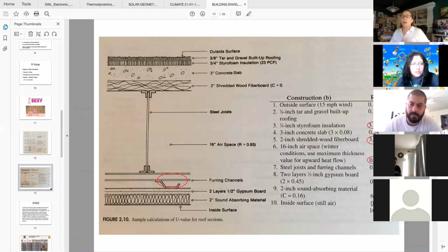Another example. I actually worked on a house on Bankers Hill here in San Diego that was right on the canyon that comes up along First, Second. I forget the name of the canyon. Anyway, it was a 4-story house, tall and skinny, and had a lot of west-facing glazing and a lot of surface area. And their mechanical system was ridiculously large for their cooling load. So we looked at increasing the wall thickness.